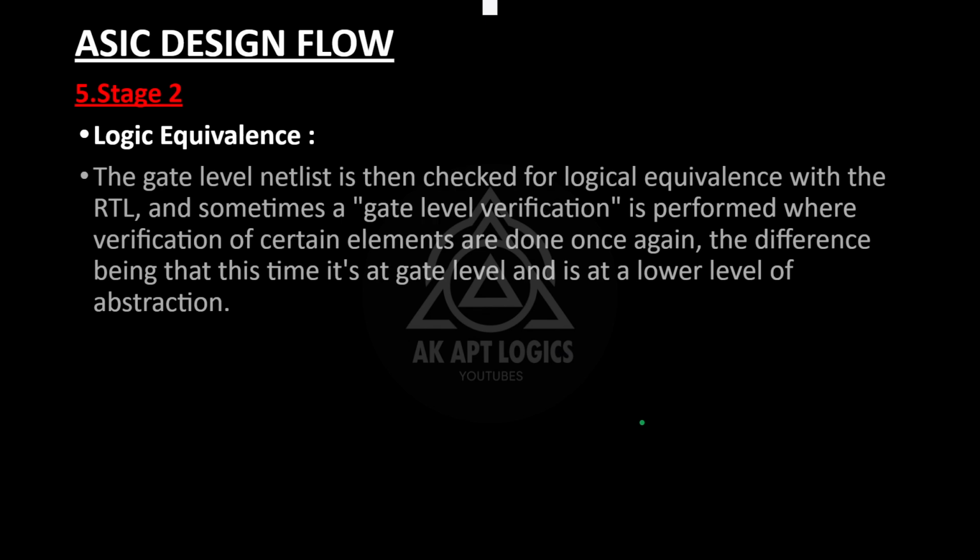Logical equivalence. The gate level netlist is then checked for logical equivalence with the RTL, sometimes called gate level netlist verification. After we generate that schematic, we perform verification again. The difference is that this time it's gate level, at a lower level of abstraction.